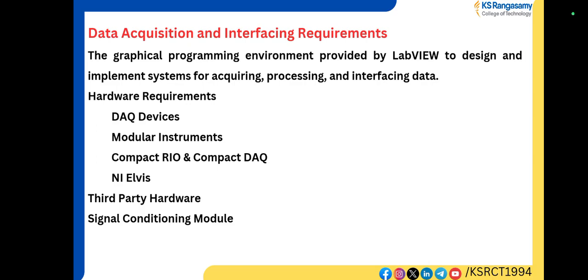First, if you consider the hardware requirements, LabVIEW is software provided by National Instruments, so we have a set of hardware provided by National Instruments. The first one is DAQ devices. LabVIEW is often used with NI DAQ devices like USB, PCI, PXI, or Ethernet DAQ systems. And then the modular instruments. Whatever instruments we need to interface, we can interface with LabVIEW and the DAQ devices, like oscilloscopes, signal generators, and digital multimeters.